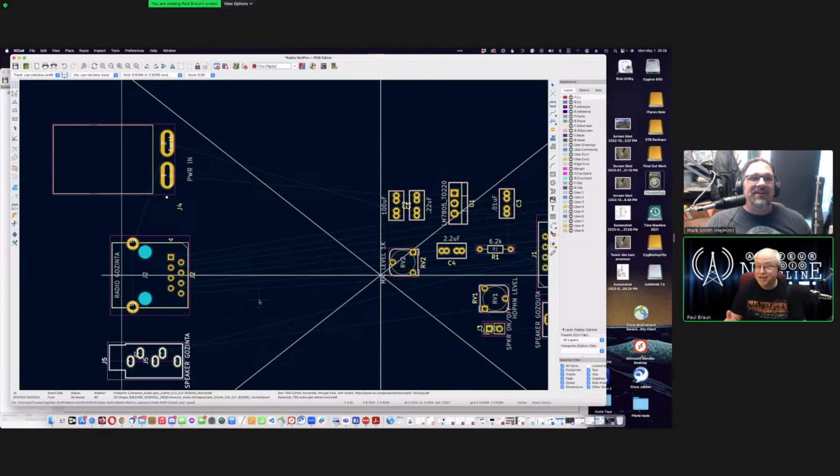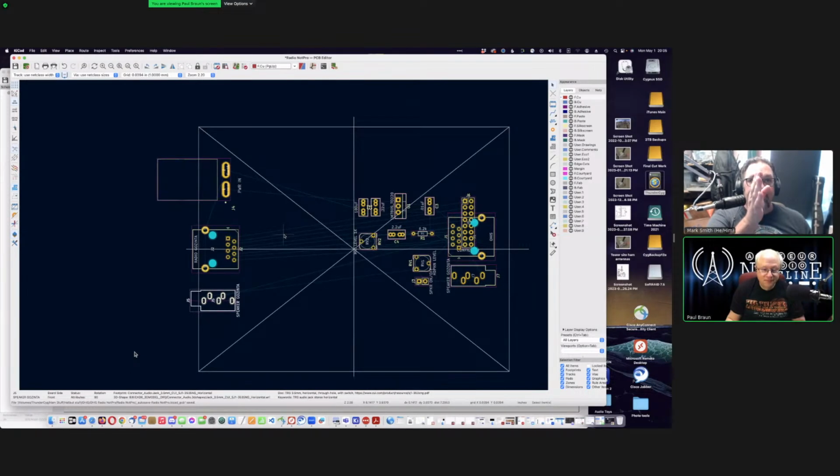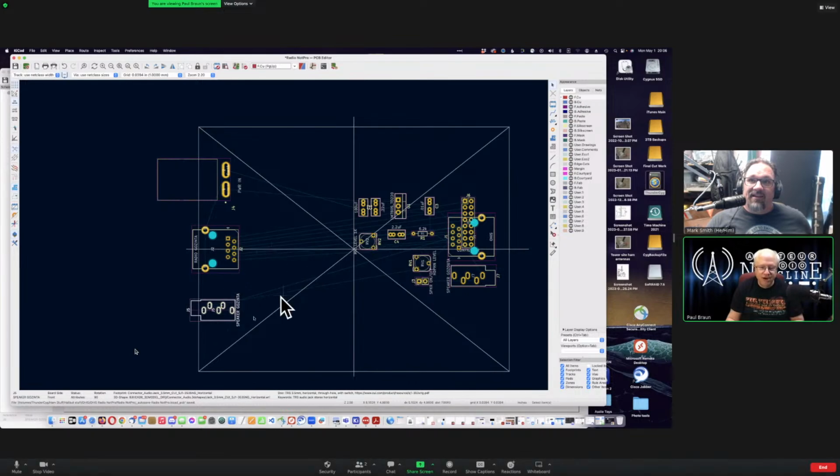Theoretically it should be centered on the center of the round part, because that's where you're going to have to place the holes in the panel. Where the rest of it is on the board is somewhat irrelevant. That connector interface is the critical dimension, because I have to drill a hole there. This is the part that goes through the hole in the panel.